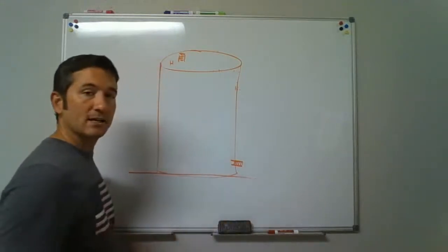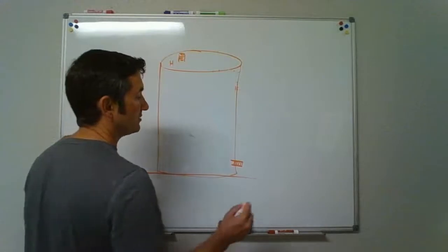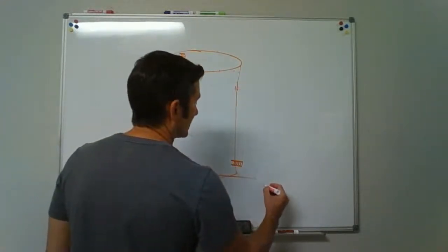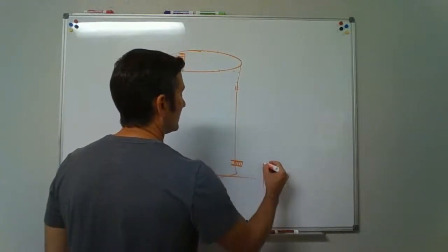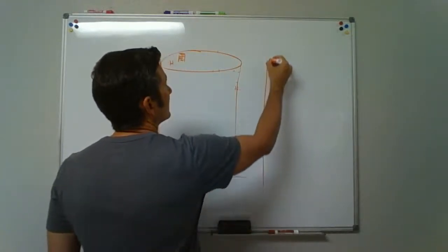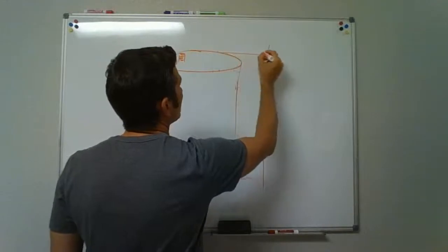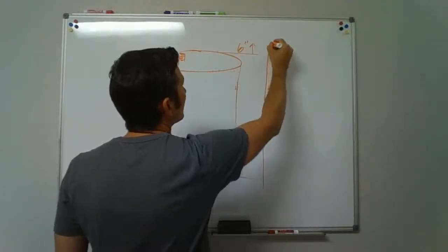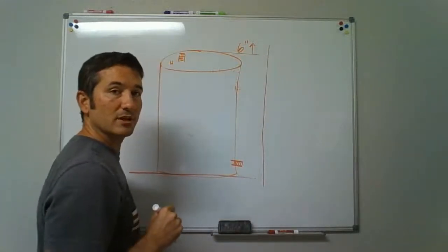When installing a vacuum breaker, as you get into chapter 6, it'll tell you to install a vacuum breaker on a device like this. You've got to run up. It's got to be at least 6 inches higher than the top of your device.